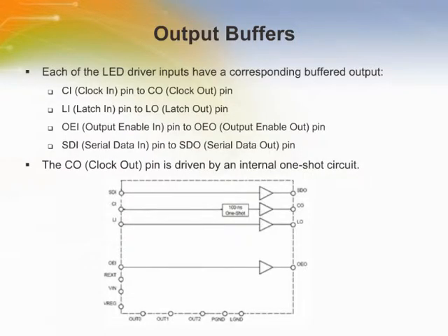This LED driver family is designed to allow daisy chaining many LED drivers of the same family. Clock, data, latch, and output enable signals are passed from one A6280 to the next without any loss of data due to duty cycle skewing or signal degradation. Output buffers drive data signals enough for long distances without needing extra hardware.